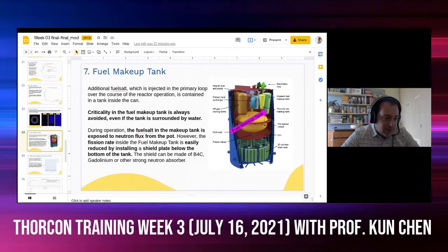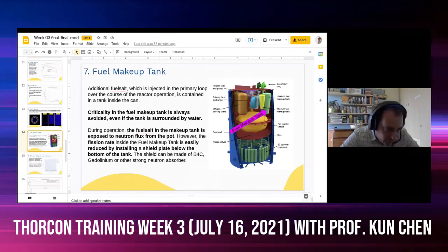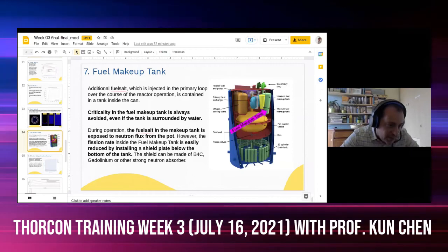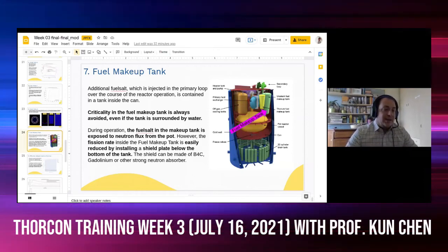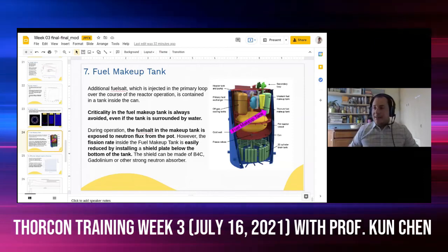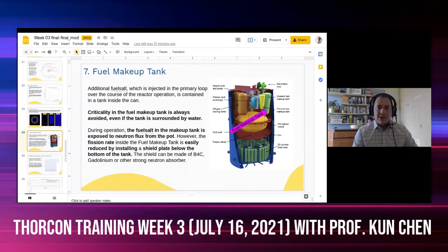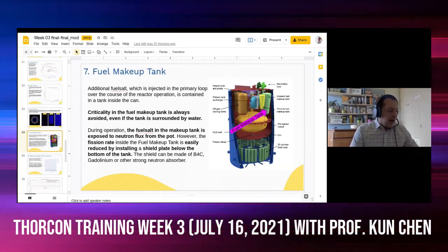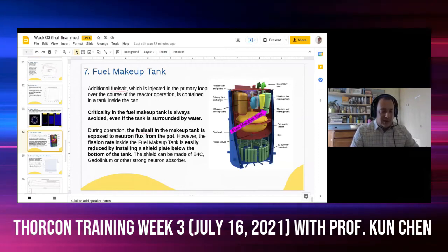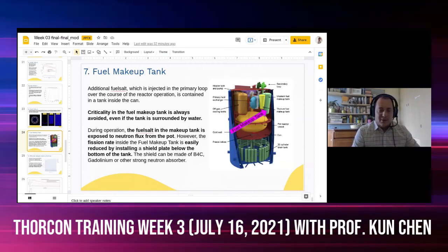How do you consider that over the reactor life, the molten salt flow can form deposit and affect the molten salt flow process and heat transfer? Yeah, that's a very important question. It is known that non-soluble fission products, let's call them noble metals for simplicity, have a preferential deposit rate in colder areas.